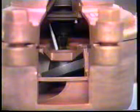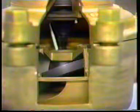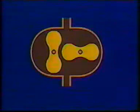Nutating disc flow meters are designed for relatively small pipe sizes and are generally limited to flow rates of 150 gallons per minute or less. Another frequently used positive displacement flow meter is the lobed impeller type flow meter. In this type of positive displacement flow meter, two lobed impellers are gear synchronized to rotate in a proper relationship.